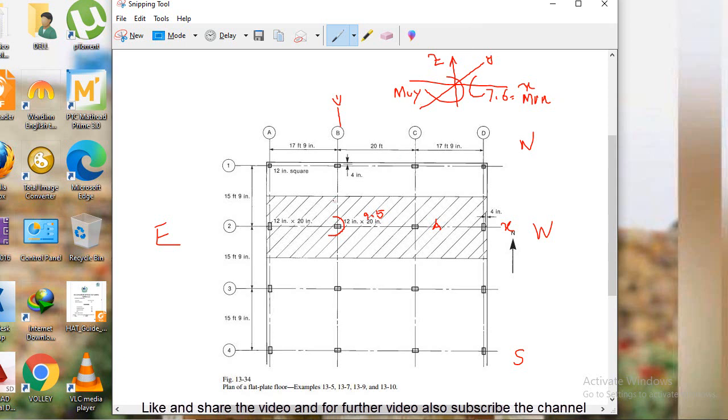Now you have to run the analysis if there is wind load or earthquake load. Once you get the moments for earthquake load and wind load, we have to add those moments to these moments, an algebraic sum, and then finally you get the net moment. So this is MUY, this is MUX. MUX is about the x axis, MUY is about the y axis.